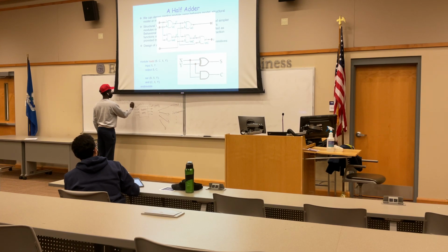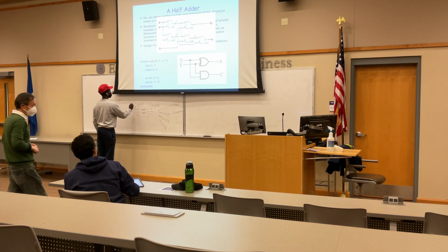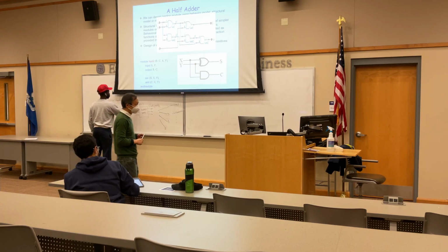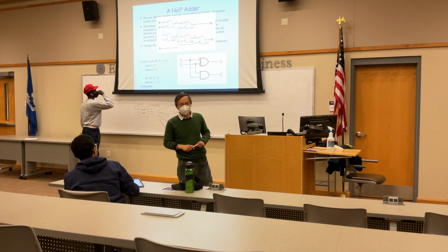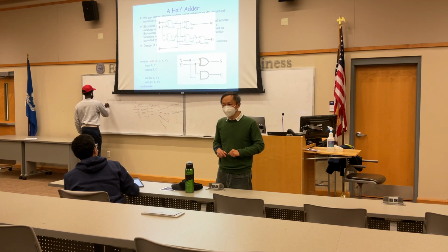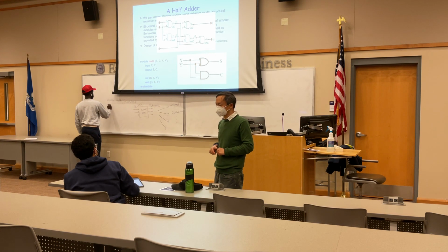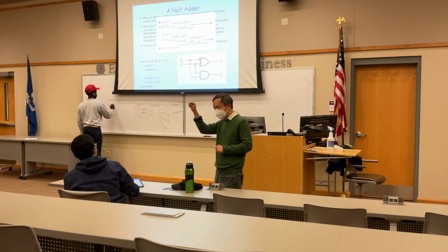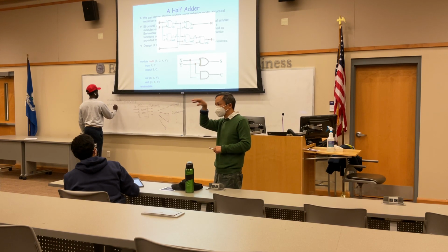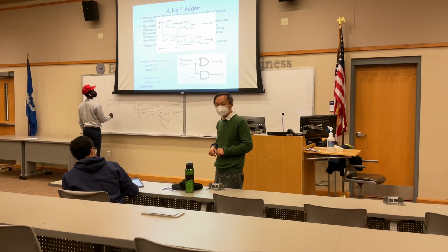Declaration by module name, with the port list, and then define the directions and the width of all the input and output ports, and then call the primitives. Specify the connections. How can we specify the connections? Using the same order as in the original primitive design.